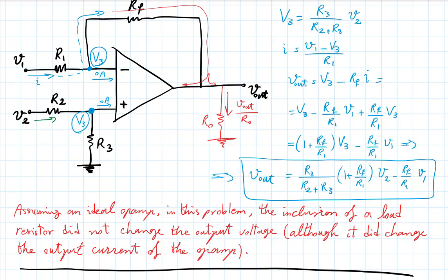If I have this, now a part of that current will have to go here, and the op-amp will accommodate the difference. And depending on how much this current is, the op-amp might have to either sink the current or source some additional current. But for an ideal op-amp, no problem. A real op-amp, as long as it's within the range that it can supply.